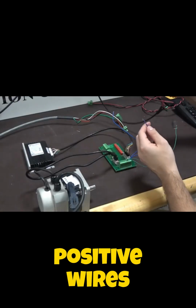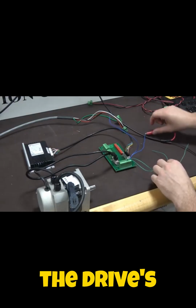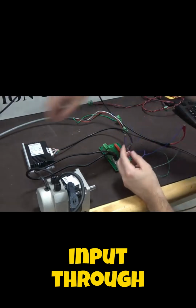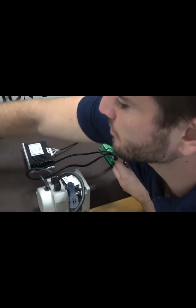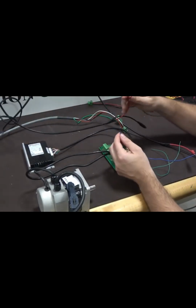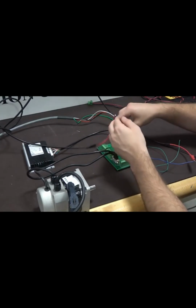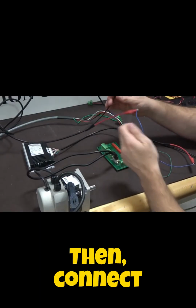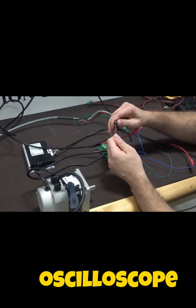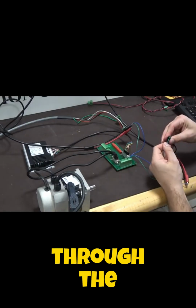Hook up the positive wires from the oscilloscope and the function generator to the drive's reference input through the blue wires as shown. Then, connect the negative wires from the oscilloscope and the function generator to the drive signal ground through the green wires.